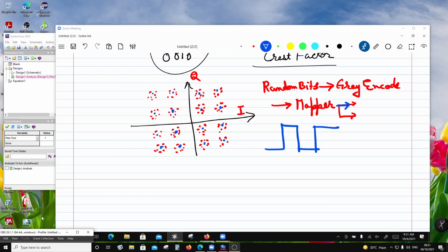So that is the nature of FFT, or the nature of the two domains. If something is localized in the time domain, for example this edge, then to represent this edge I will need more frequency components if the edge is sharp. If this edge is not sharp, then I don't need that many frequency components, right? So the bandwidth is an issue here.